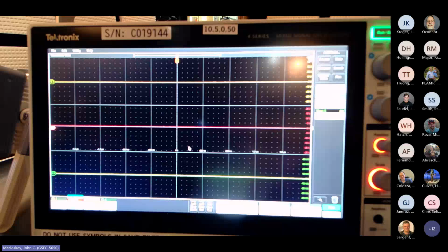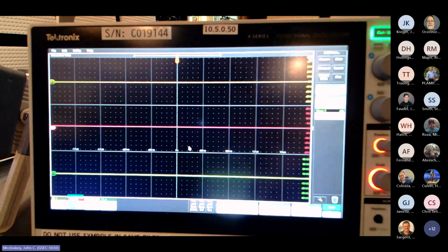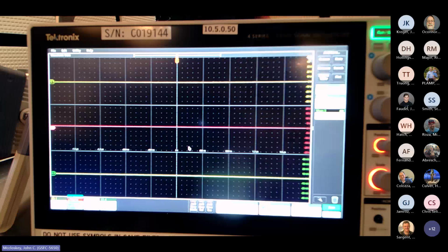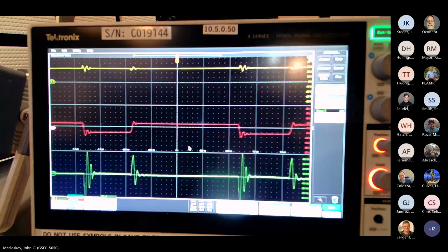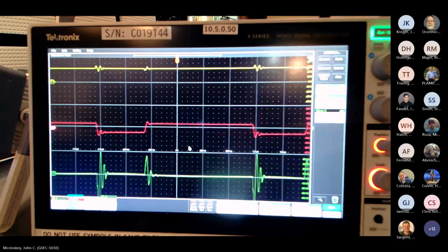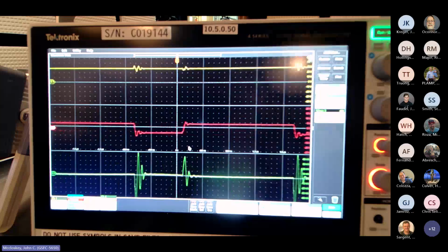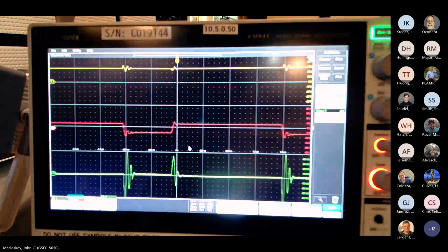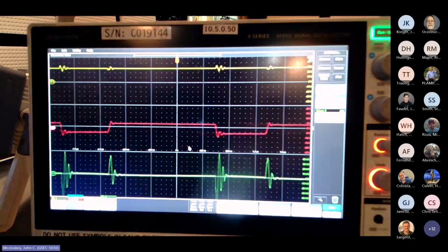And I'm going to go ahead and turn the EUT on. We don't have to worry about, like with CS114, we said our drive circuitry had to be turned on before we turn on the EUT. It's still a good idea to do that here, but it's less crucial. But it is true, our signal generator is still on, just RF is off. So, all right, I'm going to turn on the EUT now. Yeah, I wasn't sure I was going to show that, but now that it's there.